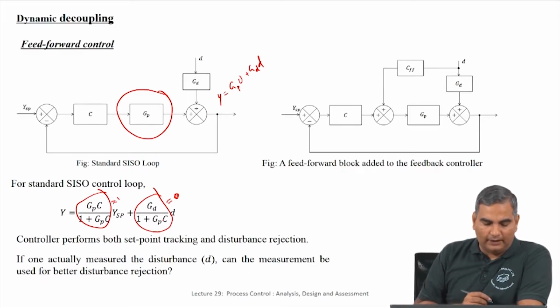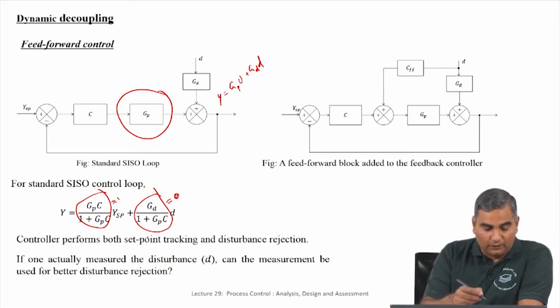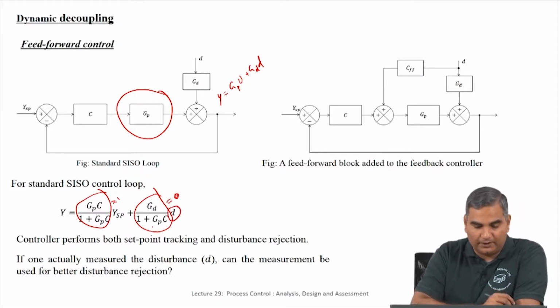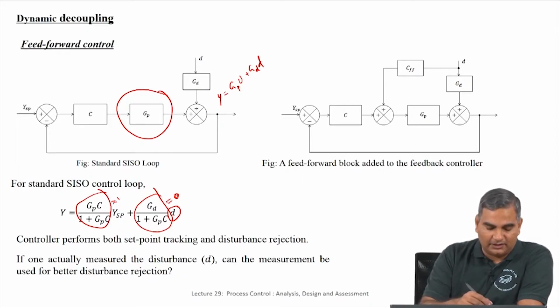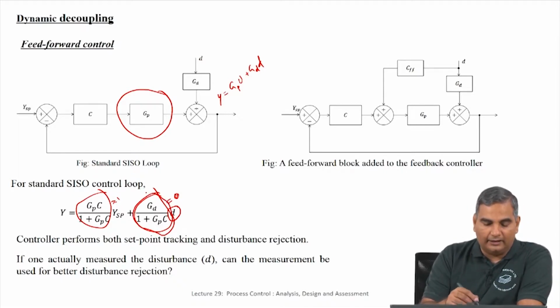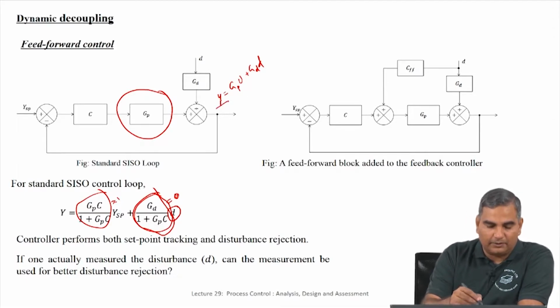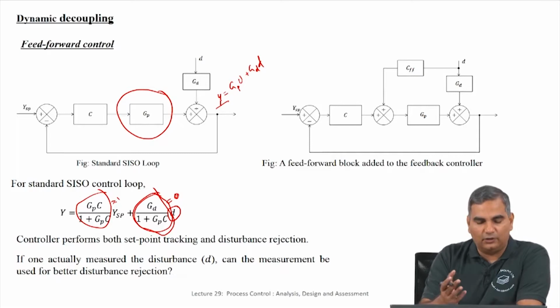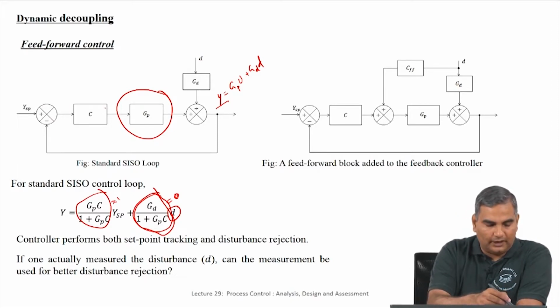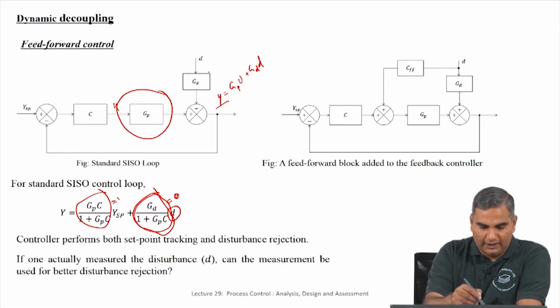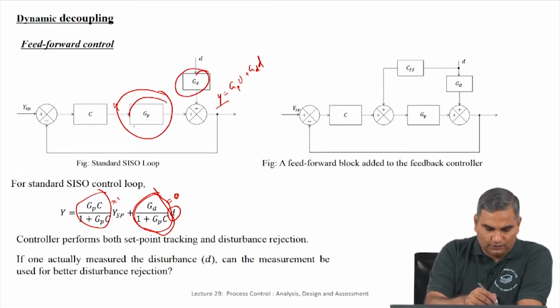So, remember, when the actual controller is being implemented, notice that I do not need the value of disturbance at all for the controller to be implemented. This is just from an analysis viewpoint, where once I implement a controller, if I want to understand the disturbance rejection characteristics, then I have to look at this transfer function form. The key idea here is, in a real system you are going to get a measurement. So, think about what you need for controller implementation. You do not need anything other than the actual measurement and a set point value which you should be given, and once you compare these two, the error is sent through the controller and U is computed. You do not need to know this transfer function. In fact, you do not need to know this either.